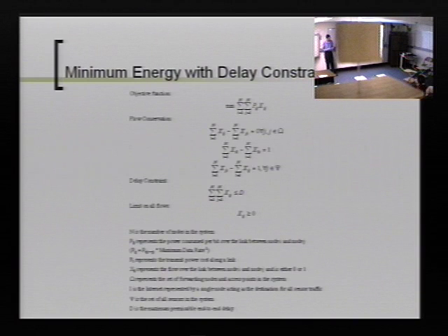Does it matter? I'm sorry? From the viewpoint of the mobile node, does it really matter which way you go? You mean whether you go to this forwarding node or this forwarding node? Well, since this forwarding node is at a much greater distance, you will need to use a higher transmit power to reach that forwarding node. So, in fact, if this mobile node goes to this forwarding node, it can save by using the lower transmit power. So, what kind of protocol are you using?